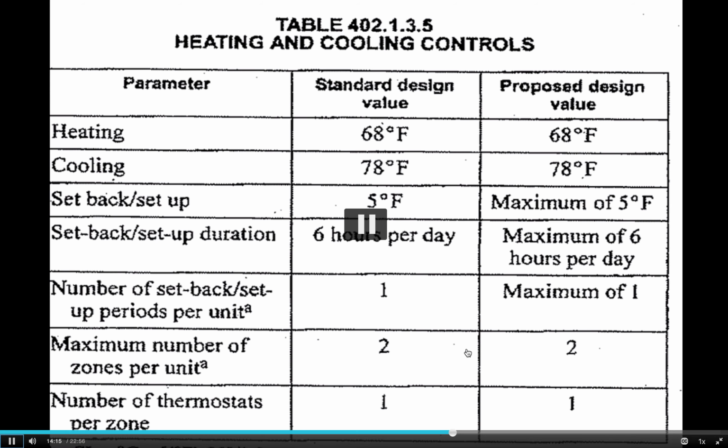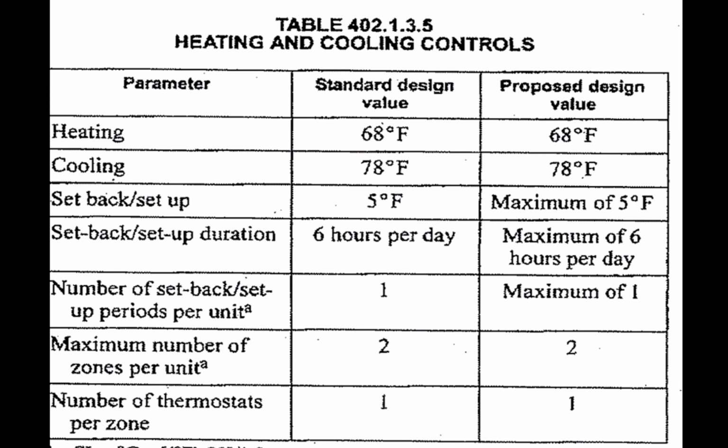And this is just a typical standard value of what the heating and control will be set to within a building system. When it's below a certain temperature, you'd like a minimum of 68 degrees, maximum of 78 within the interior. That's actually pretty high. Generally you see 72 set as the top, and 68 or 65 as the heating element. So depending on what you want as those comfort levels, it will change how your system operates.